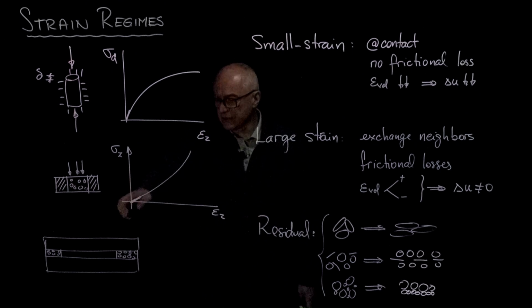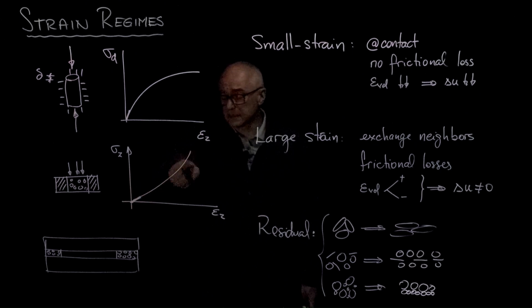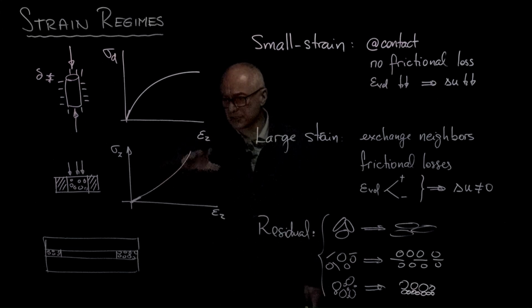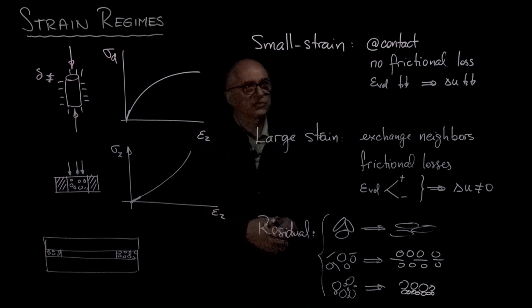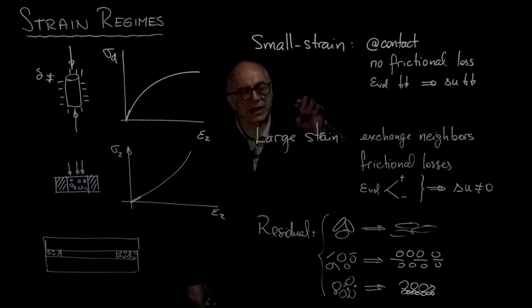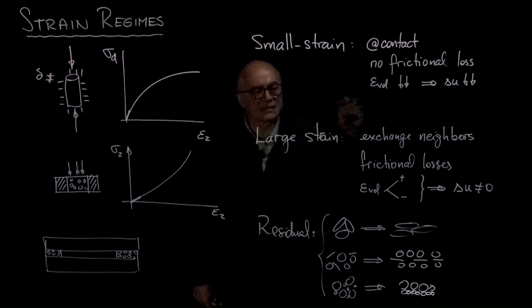Well, clearly you do have small strains, but here, for example, a clay will experience quite a lot of deformation, and in fact there is lots of particle alignment, so somewhere the K0 state or the zero lateral strain condition will fit somewhere here in the middle. Critical state will be somewhere here.